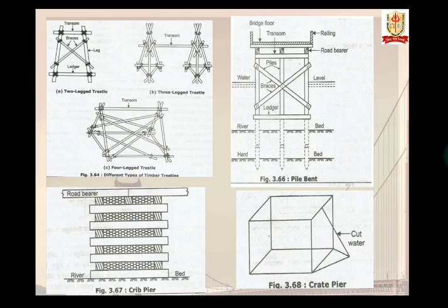After constructing this frame on the bank, it is floated to the site and placed in position by filling the enclosure of the framework with brushwood and stones. Crates are commonly used as piers of timber bridges constructed to take heavy loads.